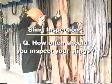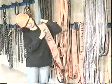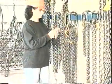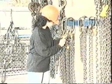You should get into the habit of inspecting your lifting gear at the beginning of each shift and before you use it. Remember, it's your responsibility to carry out this daily inspection, and if you notice a problem, then report it to your supervisor, and do not use the faulty or worn piece of equipment until it's repaired or replaced.